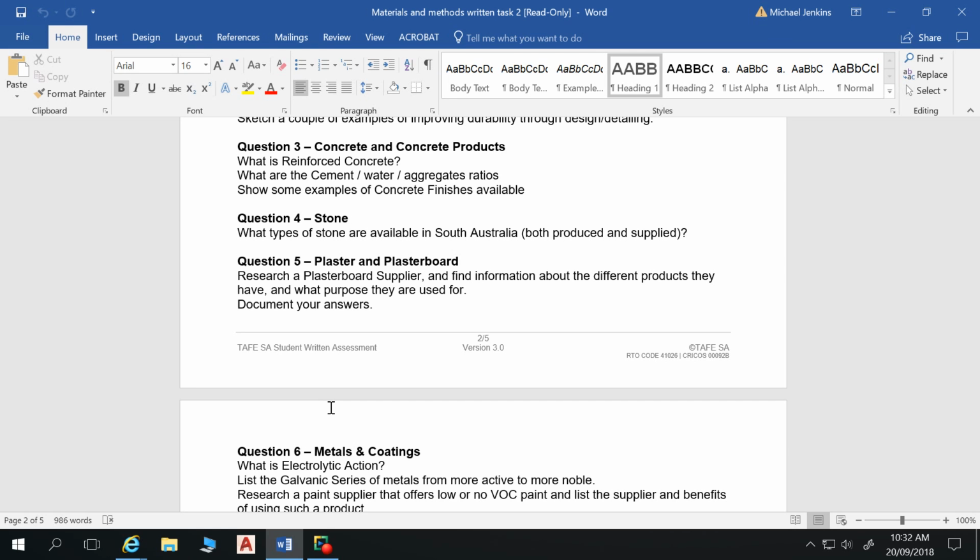Rock, yeah, rock. And we've got large aggregates and we've got fine aggregates. So sand is another form of aggregate. That's just really tiny little rocks. So when we make up concrete, we add some cement, we add some water, we add some sand, and we add some 20 mil aggregate. I say 20 mil because that's what your standard N20 grade concrete uses. Then we mix it all together and we make concrete.